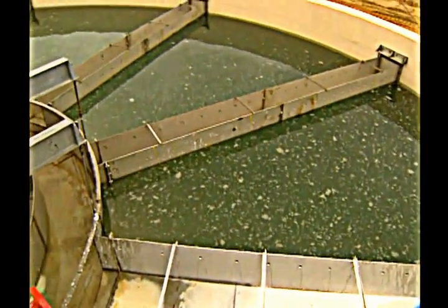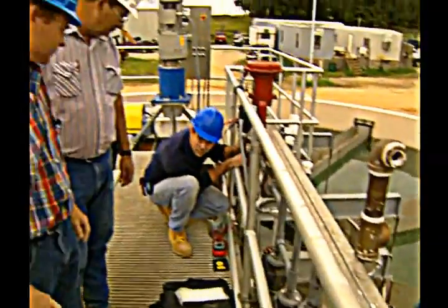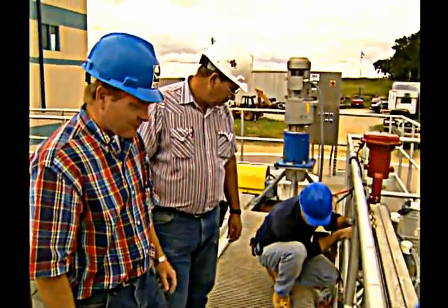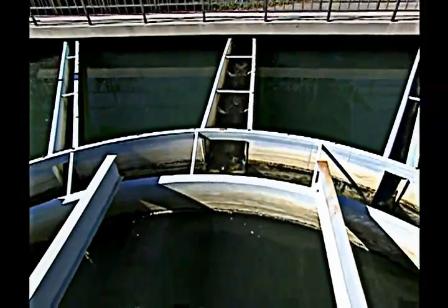As particles continue to settle out and build up, they can slough down the tube or plate and eventually settle to the bottom of the basin. There are many alternatives to traditional sedimentation, including high-rate and upflow clarifiers. Some processes combine coagulation, flocculation, and sedimentation into one basin.